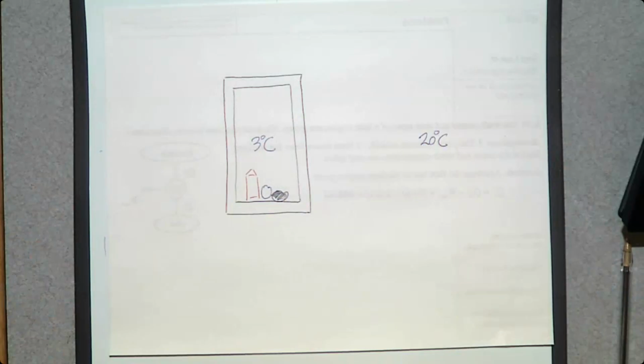To avoid that, what do we need to do? We need to have a heat transfer, the exact amount of heat transfer to the other side. So let's say there is a natural heat transfer from kitchen air to inside, let's say 20 watts. Then how much heat transfer do we need to make artificially? 20 watts. If we make 30 watts, what happens? This 3 degrees Celsius goes down. If we make 10 watts, temperature goes up.